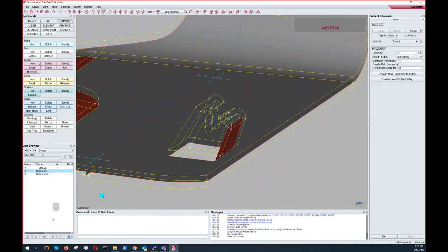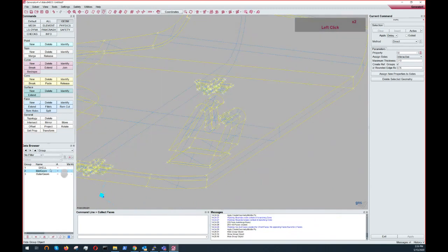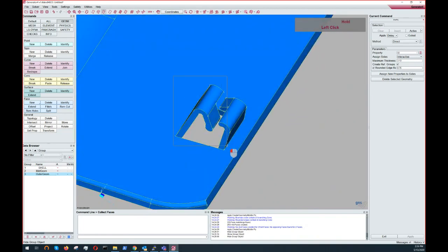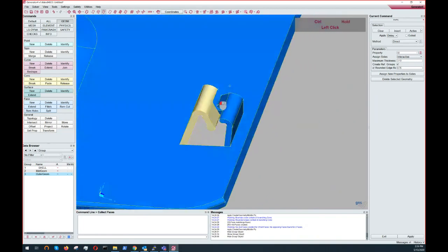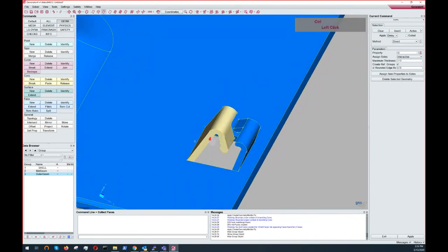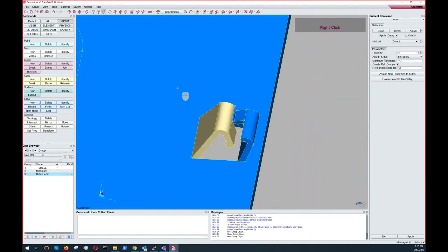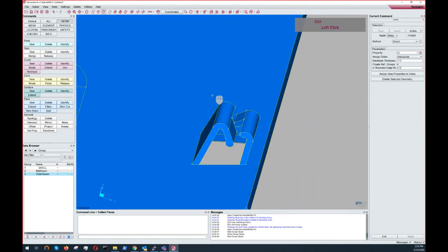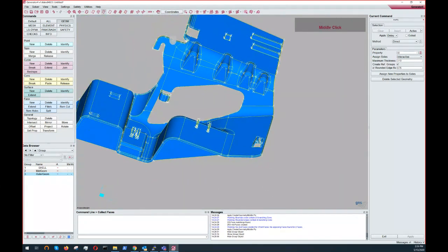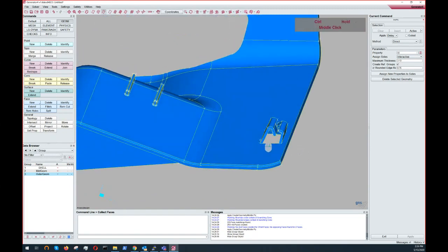So I could hide the middle geometry to better see everything and make the outer geometry again solid. And I could say, okay, just perform now this middle ply evaluation just for this area, which I forgot to check, and create the middle ply. That's one option. Maybe it's interesting if you have different areas in your volume and one it's really thin and the other one it's really thick. You may need to use different parameters here. So that's one option. But there are more.